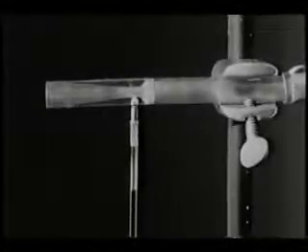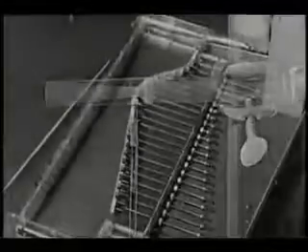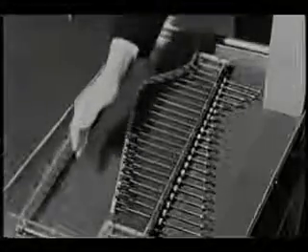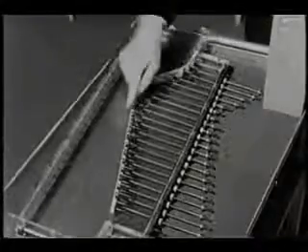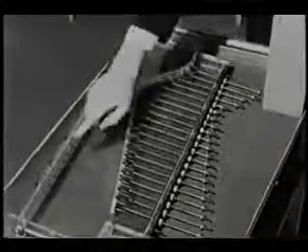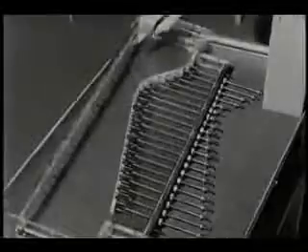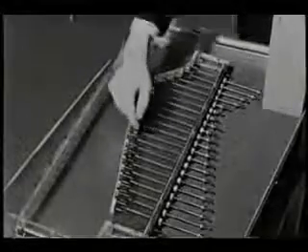To show how a venturi can produce low pressure, we have formed half of a symmetrical venturi in this special test section that has one adjustable wall. A great many static pressure taps are connected to manometers. Here it is set up for test. These are inclined manometer boards to show the pressure distributions on the two walls. We will observe the lengths of the water columns looking down from a position directly above.